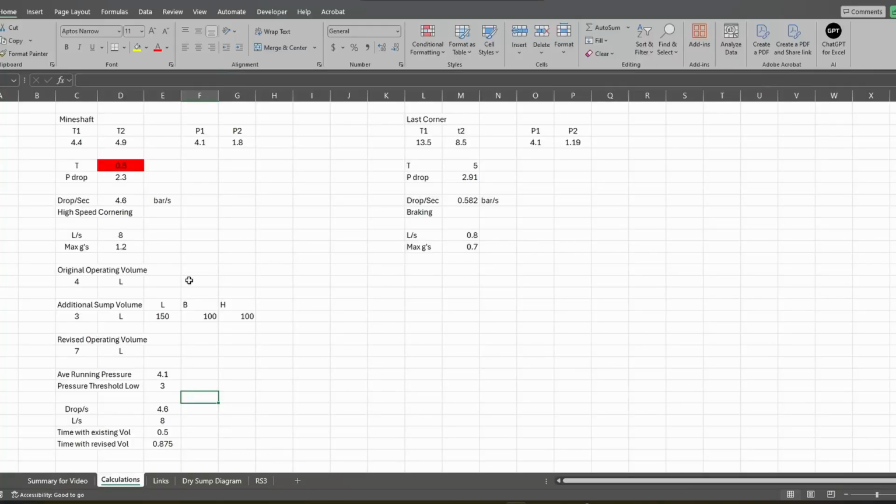If it loses a point of pressure per second, kind of thing. I started doing the calculations, and basically what I got to was it happens so fast that it didn't make sense to just purely add volume in terms of oil. It happens within 0.1 of a second. You go from oil pressure to nothing.